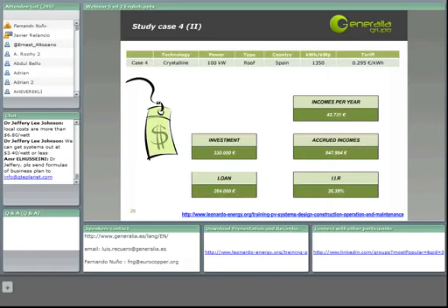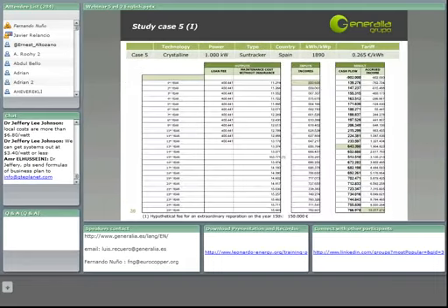whereas if we are considering a roof installation in Spain for the same size, we can get a higher internal rate of return of about 26.4%. Obviously, as we have more energy in Spain and the feed-in tariff is more or less the same, we can get higher internal rates of return in Spain than the ones that we get in Germany. Anyway, we have to check the feed-in tariffs for the year when we are executing our facility, because it can vary a lot from one year to another.